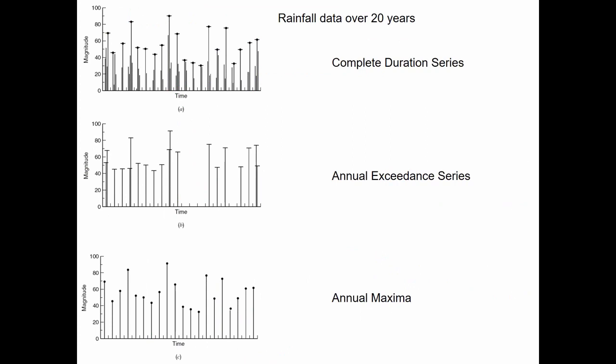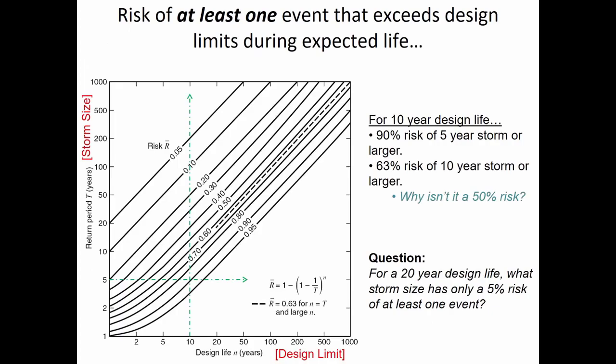Yeah, go ahead. Are those structures, like for an ELV, going to have really long design life? How about those dams? Yeah, dams are in place for 100 years or even longer. That's right. So it's probably not going to be good to use 10 or 5 or 2 years on that part. Well, where we do use this chart and where we're designing things for 5 and 10 year, it would be flood control like levees or a diversion. There are a lot of other flood control structures besides a dam where you maybe are going to just protect against, designed for a much smaller storm. So you're right that the dam, because the consequences of failure are so expensive and so risky to human life, you just design that for anything that can be thrown at it.